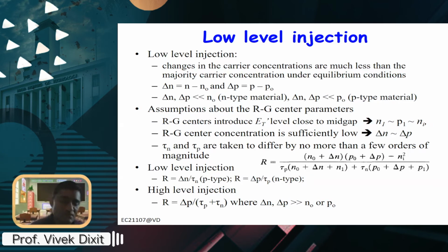You diffuse phosphorus there, and it will interact with the impurities and attract them to itself. Because we are diffusing phosphorus from the bottom, these impurities will be attracted to that particular site, so the upper layer of your semiconductor will be free of the impurities.